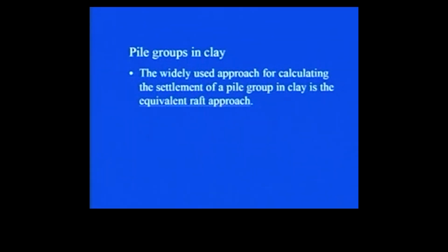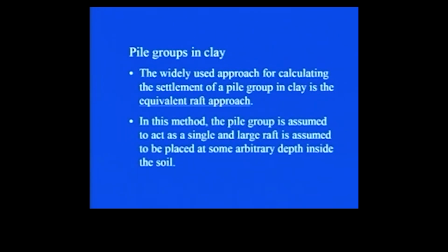The widely used approach for calculating the settlement of a pile group in clay is the equivalent raft approach. This is a very important approach that you must understand properly. As the name suggests, it is not exactly a raft, but what we are considering as an equivalent raft. So, let us try to see what exactly is there in this particular approach.